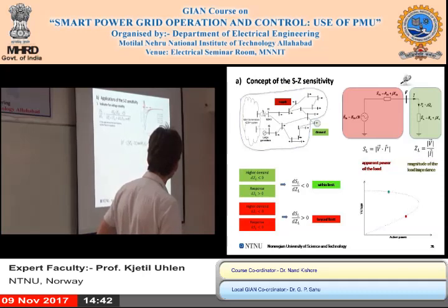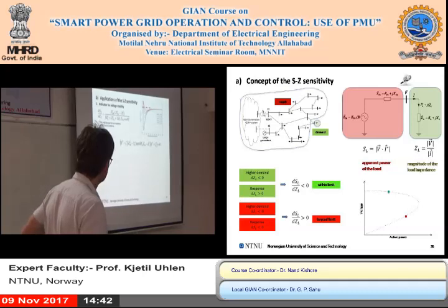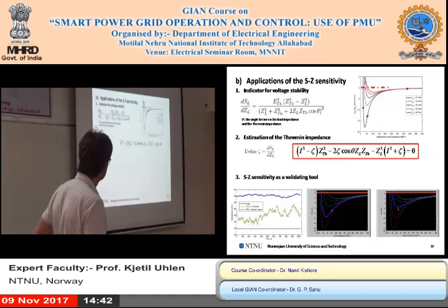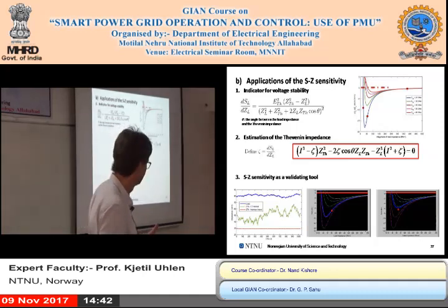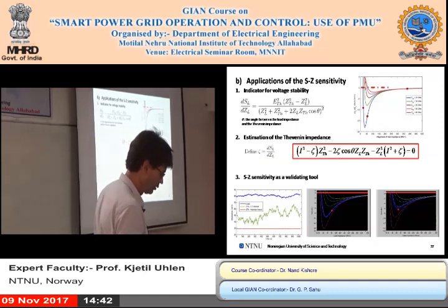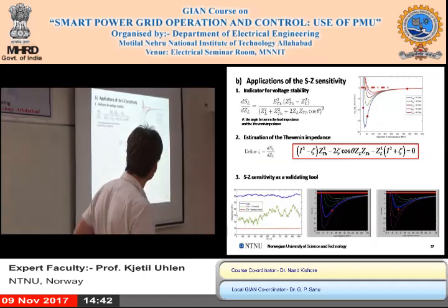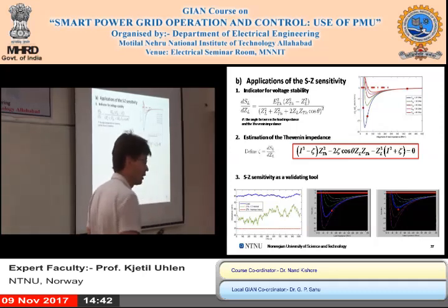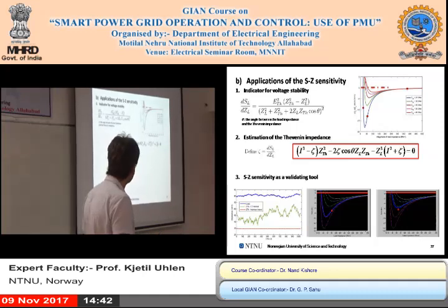And if you do some math on that, using Kirchhoff's laws, this is described in a paper, to be published very soon, and in a PhD thesis. So that should be available from us. You can express the sensitivity as a function of the internal voltage, Thevenin impedance, load impedance, and the power factor.